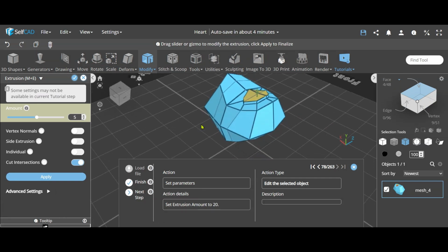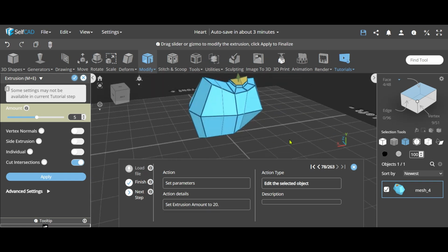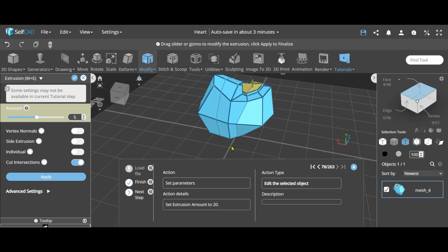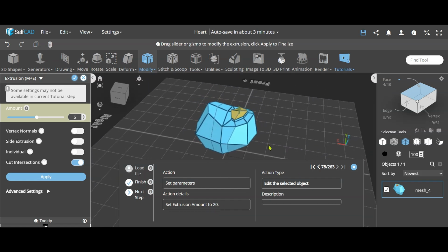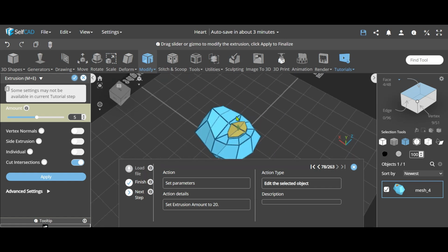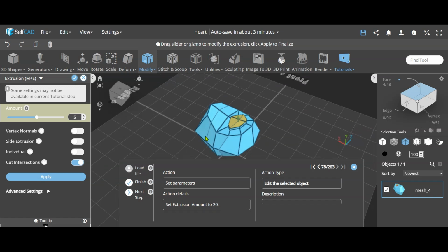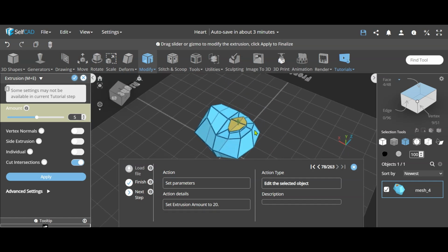Instead of making two shapes and then connecting them using Boolean operation, stitch and scoop, or using more advanced tools like Loft, which typically would give you a very messy object with high detail, very high poly, the benefit of this is that you just shape the geometry, and you get a very low poly result. That's basically why this is low poly, and this is called surface modeling. You basically just edit the surfaces.